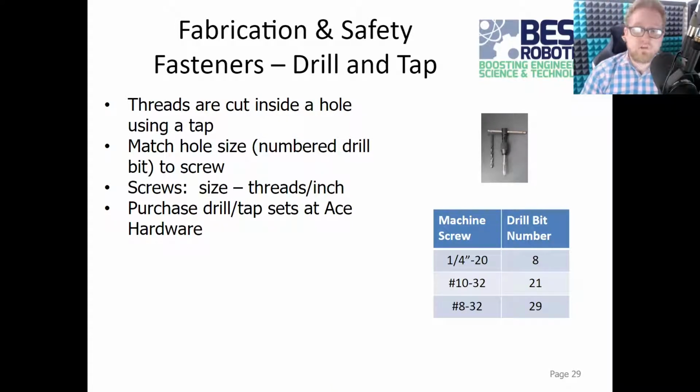You can also tap the aluminum blocks. So this allows you to put threads into the block and put a bolt in as if it were a nut. This is a hand process and is fairly advanced. Anybody can do it with practice. However, it's very, very easy to mess up.